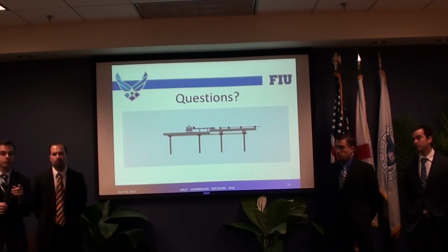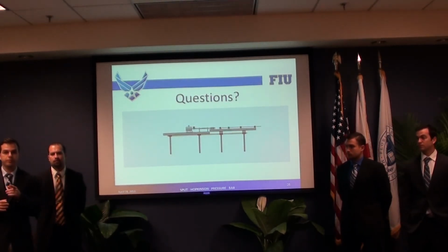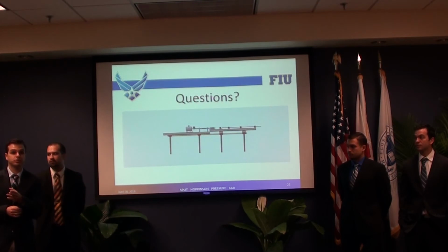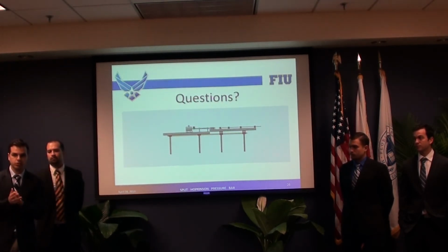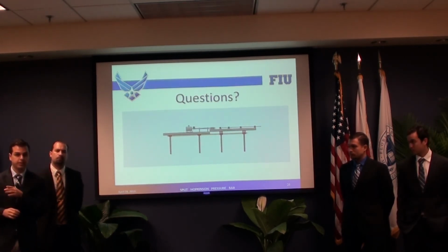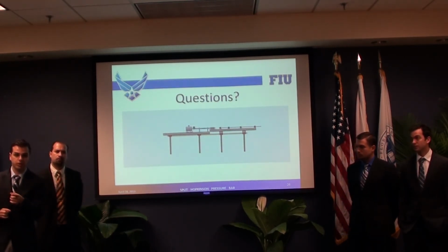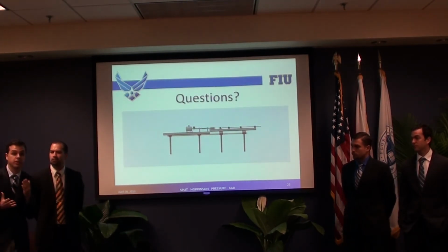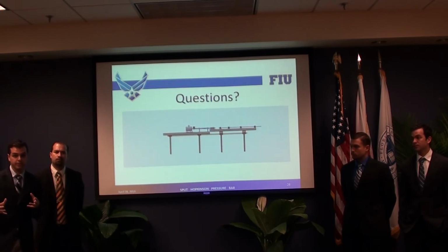It's the stress wave going radially in the bars, the ringing in the bars. So we have a stress pulse going down the bars axially, and as it goes down axially, it goes across radially as well. So that effect would be minimized if using a 100 kilohertz time base.